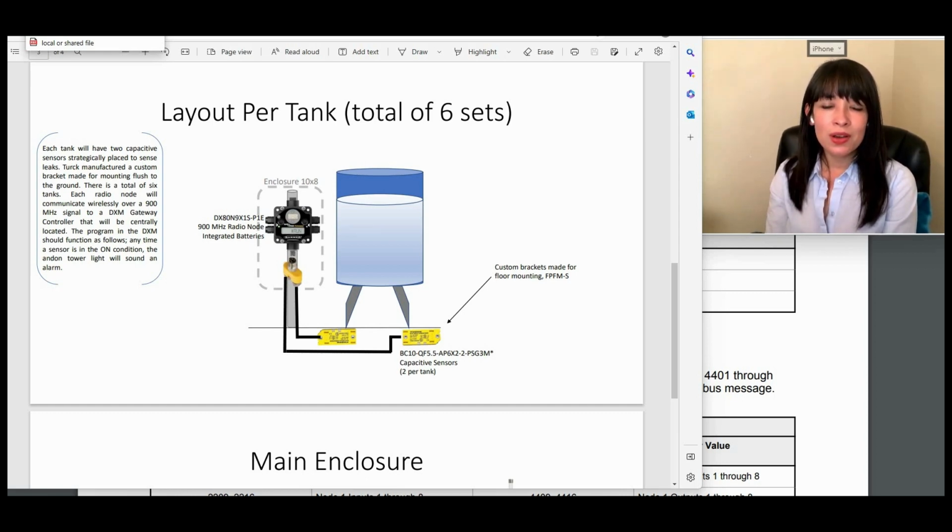And for today's video, I want to show you how to do alternative Modbus register mapping in the DXM configuration software. I want to show you how to do control logic, math logic, and how to set alarms with threshold rules. Recently I had an application where I used all of these rules, and I thought it'd be the perfect opportunity to make this video and show you how I solved this problem and how I went about building my program, because I believe that I was pretty efficient with the amount of rules that I created. So I hope this helps you.